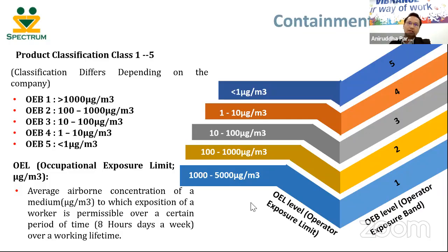For example, for oncology, if you were to group the entire list of products, it may happen that your batch sizes come up to, say if you are making an OSD facility, a 50 kg suite for granulations, or maybe an 80 kg suite of granulation. But if we were to look at segregation based on the OEB bands, it may turn out that few of the products are in the OEB3 band.